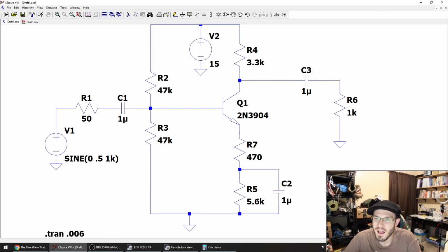Okay, so that should help you to develop your LTSpice model, be able to run it, know where to measure and where to look at things. You're going to be measuring in between the cap C1 and R1, and you're going to be measuring the applied voltage to the load between C3 and the 1K, so right in between here. Aside from that, it's just some caps and resistors, and you should be able to calculate this all by hand.